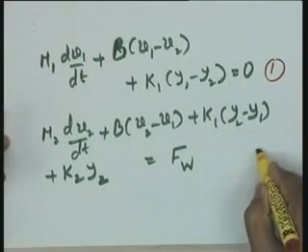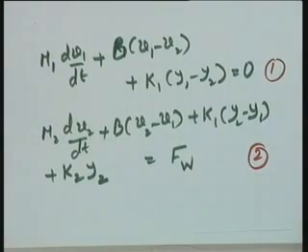Fine. If the first step is over, that is, I have written the two differential equations, equation 1 and equation 2, now this constitutes the complete dynamical model of the system. The only thing is that this model may not be convenient for use. I may be looking for a state variable model. If that is the case, help me, what are the state variables you propose? In this particular case, two masses are there, and recall the statement, normally the displacements and velocities associated with the masses constitute an independent set of state variables for a spring mass damper system.